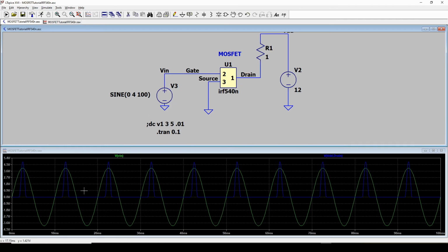So now we're going to have to figure out how we get this so that the input never goes negative. I've got a negative sine wave, but I want to shift it up so this negative 4 down here is greater than 0, so that I can take this sine wave and amplify it to make it into a positive sine wave on the output.